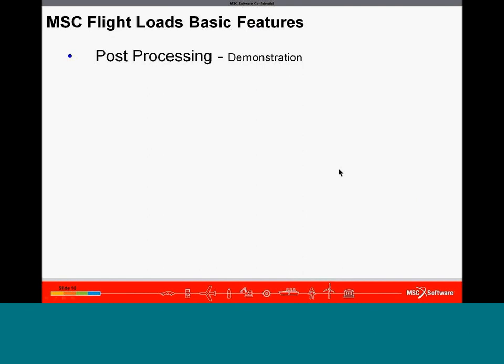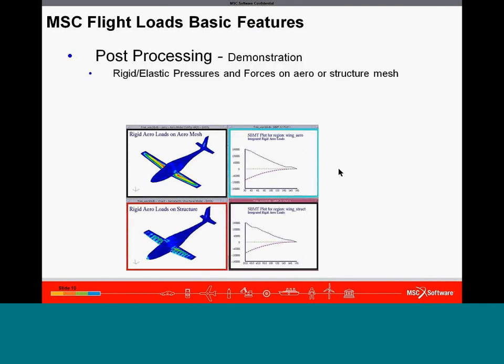On the post-processing side in Flightloads, we can look at the rigid and elastic pressure distributions on the aero or the structural mesh. We can look at deformations on the aero mesh. And again, we can look at things like animations, and the ones that are always fun to look at are the flutter mode animations. It's always nice to see those complex eigenvalues animating.